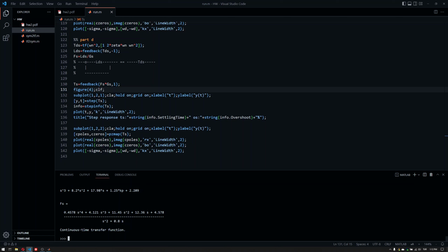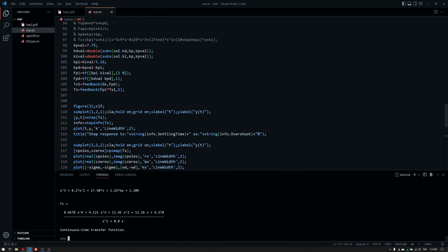But model matching controllers are also a good starting point in determining the controller structure or seeing what the result could be. And if you have an adaptive or a learning mechanism in your system that updates your model prediction, if you can predict the model, feed it to the model matching controller, that would be another story. So this is basically it.